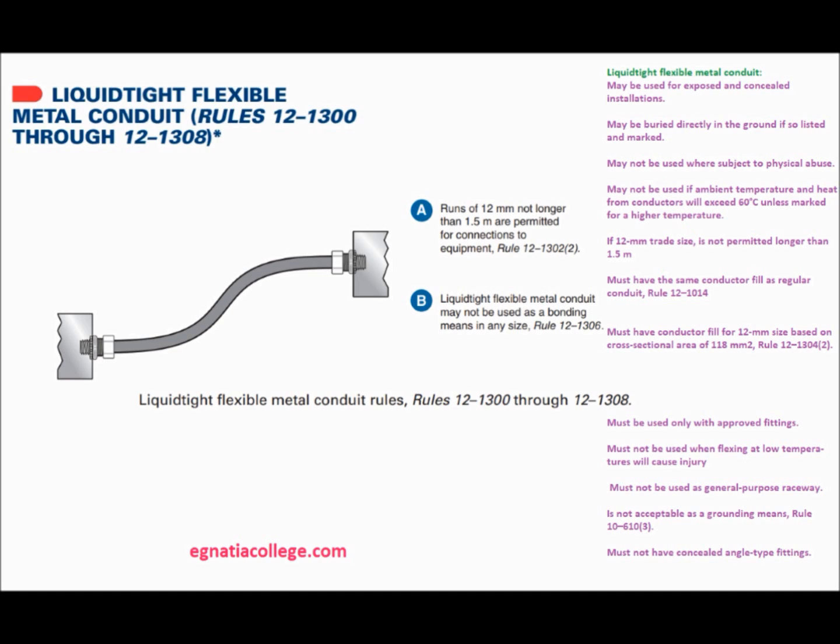Must not be used when flexing at low temperatures will cause injury. Must not be used as general-purpose raceway. Is not acceptable as a grounding means. Must not have concealed angle-type fittings.